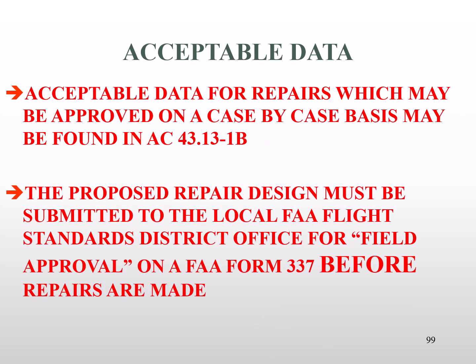The question becomes, how does acceptable data differ? Well, acceptable data is generally good ideas. Typically, the 4313 is a good source for that. Acceptable means it's a good practice, but it's not data that's been approved or okayed for your specific need on that specific airplane.